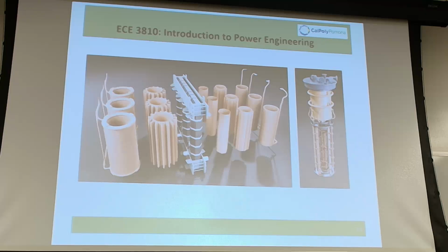There is a phase where they dry it, because you want to extract every molecule of moisture that can be trapped. The last thing you want inside the transformer is any type of water particle. Any moisture, once the transformer is energized in the oil, can cause little bubbles to develop. They don't necessarily have to be large bubbles, they're tiny bubbles, and it can damage the transformer. You can have a flashover. So the baking part, like I said, is a long process.